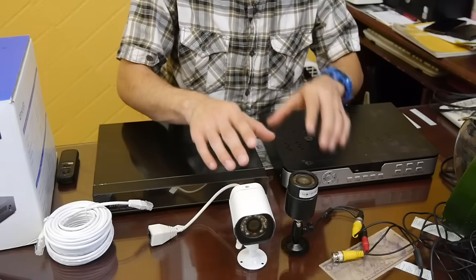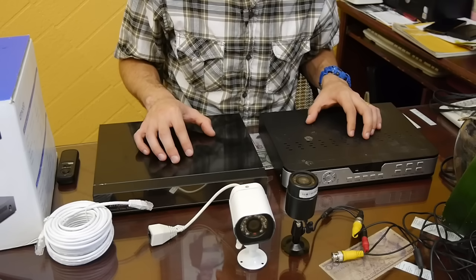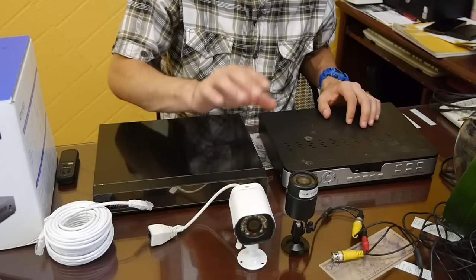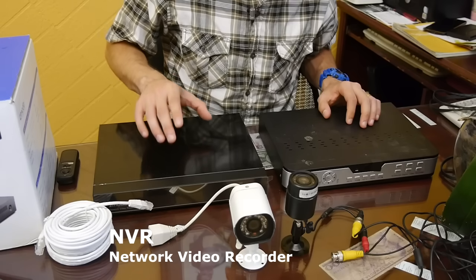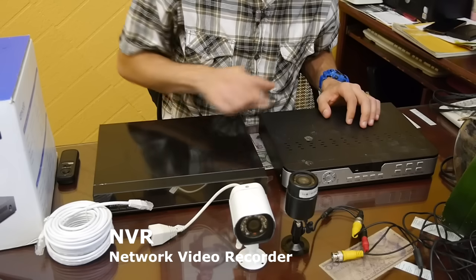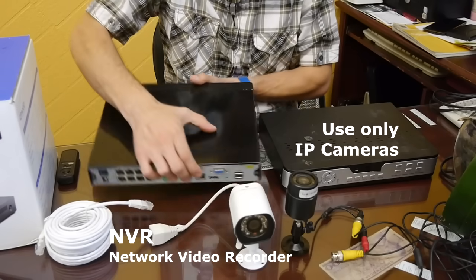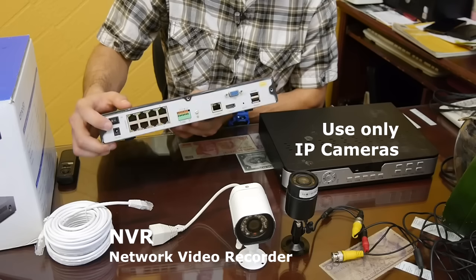Just like there are 2 types of security cameras, there are also 2 types of DVRs. When you hear the word DVR, it will always refer to a digital video recorder meant only for analog cameras. A DVR for network cameras is called an NVR, which stands for Network Video Recorder. Even though it's called an NVR instead of a DVR, it's still a digital video recorder. An NVR is built from the ground up to accept only IP cameras, as all of the inputs on the back are for network cables.